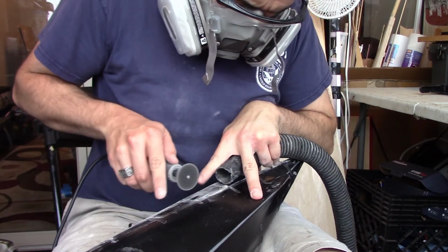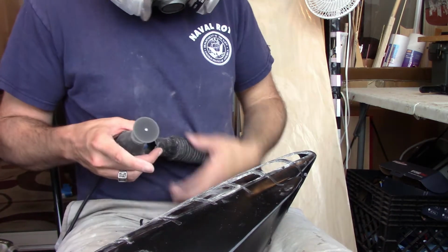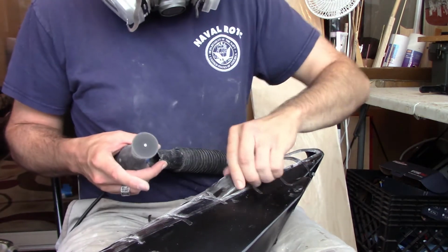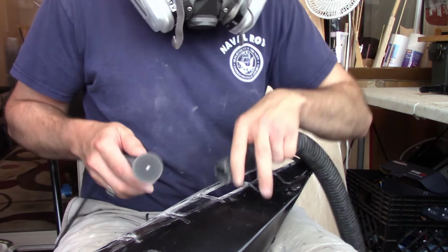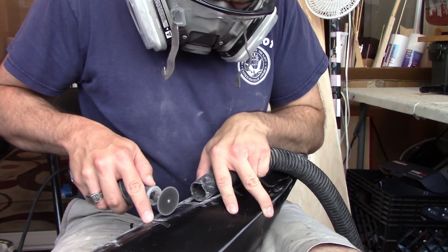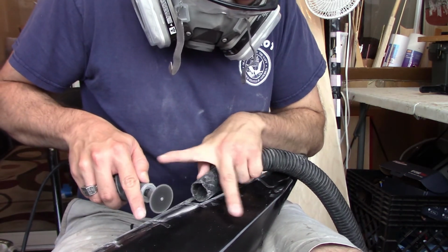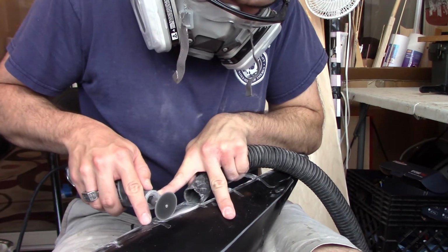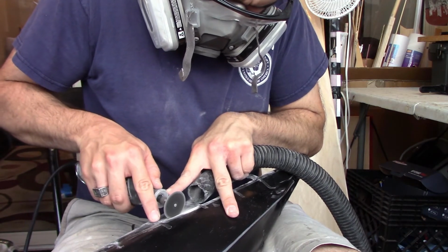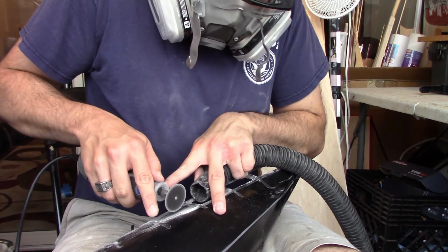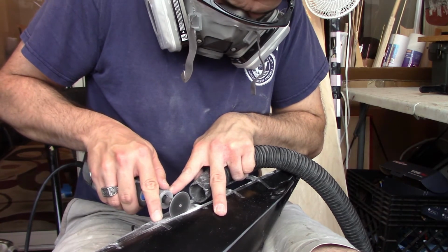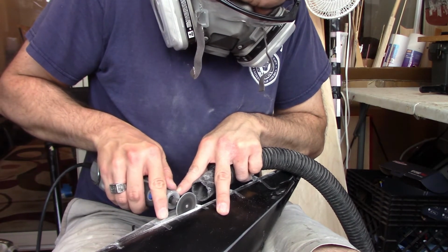When you're making the last cut for a window, you always want to be careful because when it breaks free, it's more likely to cause the wheel to jump. So when you're making that cut, try to make it on a joint that's less critical, so that if it jumps, it's going to jump into the bottom or something where it doesn't matter quite as much.